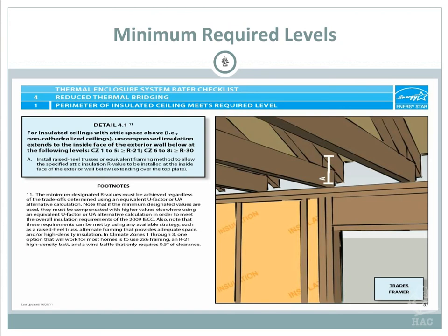Zone 6 to 8, again, you have to have equal to or greater than an R30. So if you're spraying an R30 minimum, you have to have at least a 10-inch space right there where that A is in that diagram. So in order to have an R30, you're going to have at least 10 inches or 12 inches of space. So you can't build the way we used to build and be able to meet that Energy Star or the performance measures anymore.